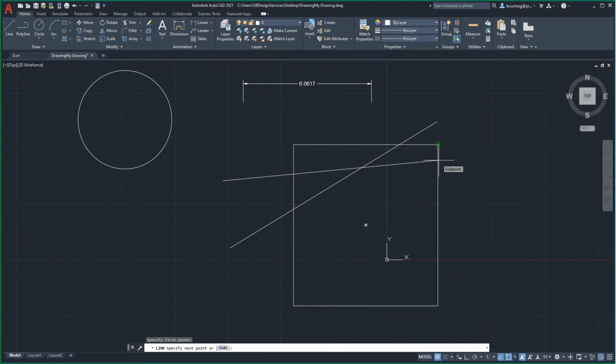The software will indicate any given snap point when you are within a certain distance of that snap point location. There is a certain level of trust value the user must develop to trust that when the software presents a snap point, and in this case I choose endpoint, that the software will snap, in this case my line segment, to that snap point that was detected.